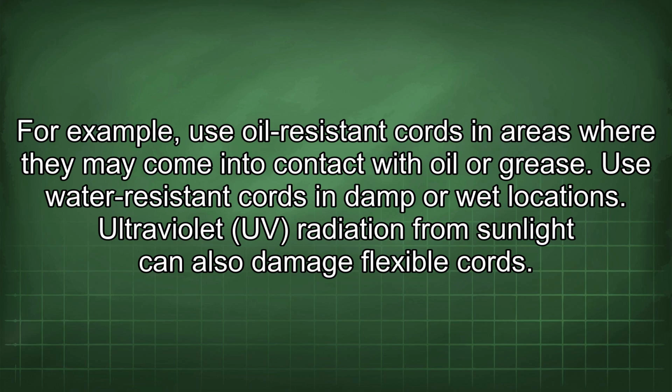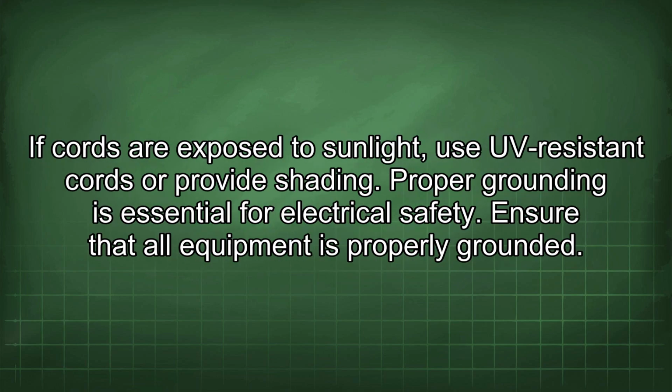Ultraviolet (UV) radiation from sunlight can also damage flexible cords. If cords are exposed to sunlight, use UV-resistant cords or provide shading.